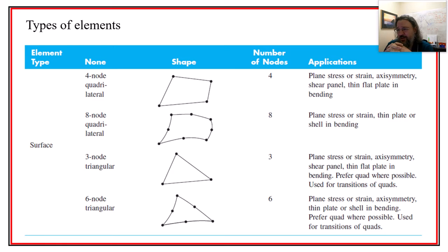A company like ANSYS has a lot of elements to offer, lots of elements to choose from. There's probably a few that are the go-to ones for general stuff, but SolidWorks kind of hides that from you. By the way, I should say, you can make stuff in beam elements, right? So you really have three kinds of element types in SolidWorks Simulation. You have beam elements, shell elements, and then the basic solid tetrahedron element.